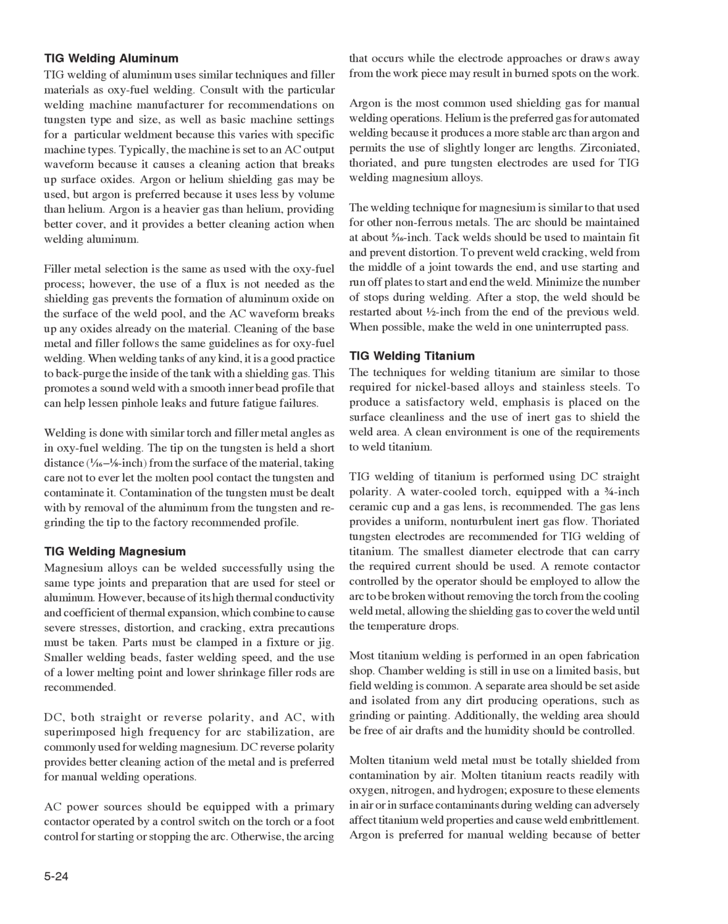TIG welding titanium. The techniques for welding titanium are similar to those required for nickel-based alloys and stainless steels. To produce a satisfactory weld, emphasis is placed on the surface cleanliness and the use of inert gas to shield the weld area. A clean environment is one of the requirements to weld titanium. TIG welding of titanium is performed using DC straight polarity. A water-cooled torch, equipped with a 3/4 inch ceramic cup and a gas lens, is recommended. The gas lens provides a uniform, non-turbulent inert gas flow.